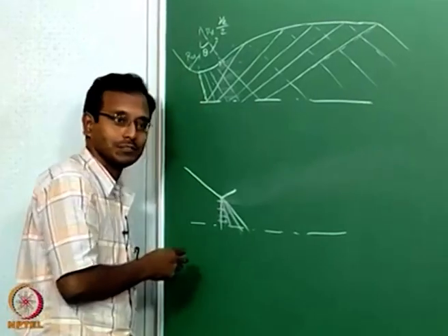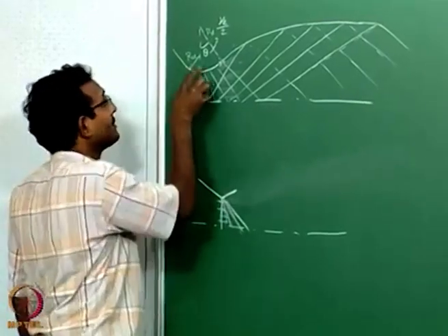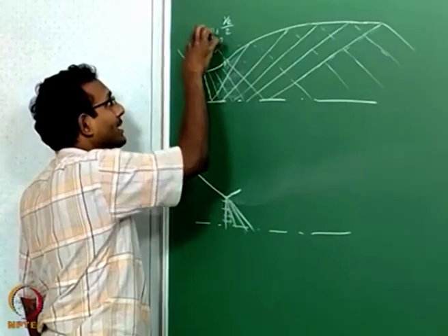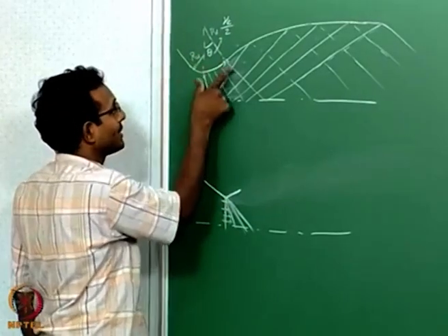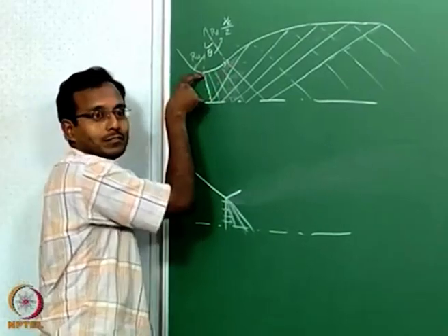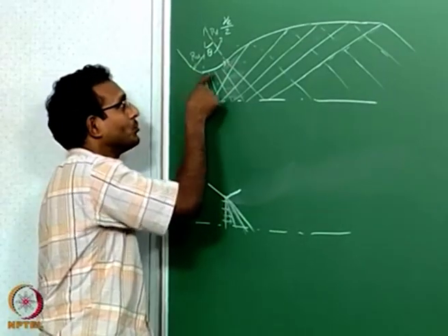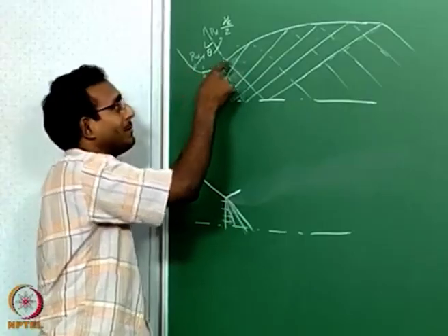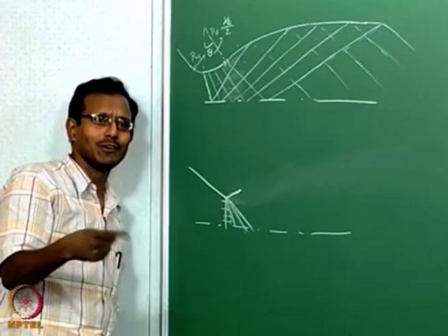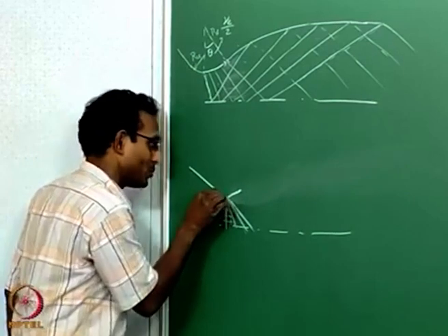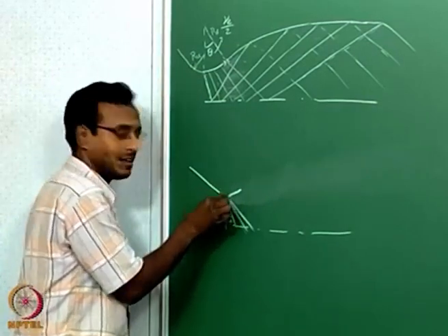I will directly do this. So what that means is, this R downstream, that radius is also now shrunk to 0, okay, which means all these expansion fans are now coming from this one corner. Instead of it being a smooth wall, smooth expanding wall, it will be a point expansion. That is the only change. Point expansion we already had a routine for it. So you just have to go and put so many points exactly at the same location with that kind of expansion.